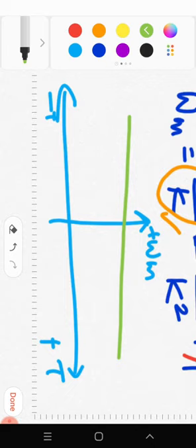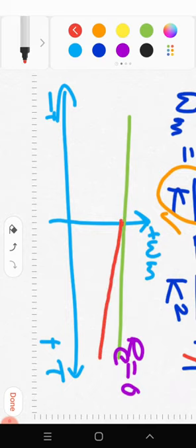So this is a rated operation, we can say, natural characteristic. Now if we add resistance externally, so obviously natural characteristic means this is with R equal to 0, external resistance 0. And if we add external resistance, then there will be another characteristic, with a slight increase in the resistance.